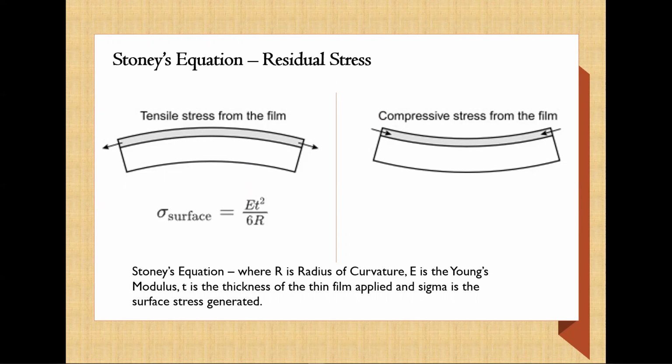So some of that thermal effect could already be there. So we would need to check the residual stress effect of the material prior to the coat and then post-coat as well.